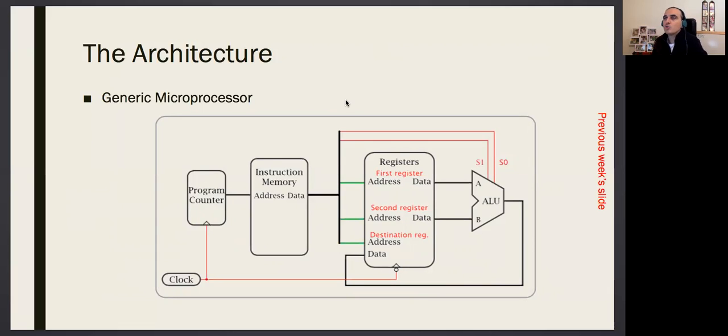So a good question could be, well, most microprocessors are single core. So how come they do it? Well, this is a complicated question. This is related to some embedded system stuff and operating system stuff, so other courses. Actually, it does something called scheduling. It does one work and it does another work. It just switches between tasks. However, regarding your question, if you're doing complex operations, like an operating system, like a smartphone, multiple cores are a must.